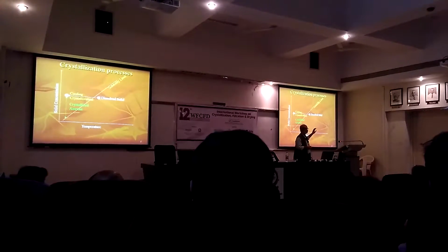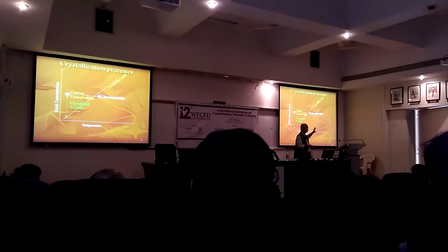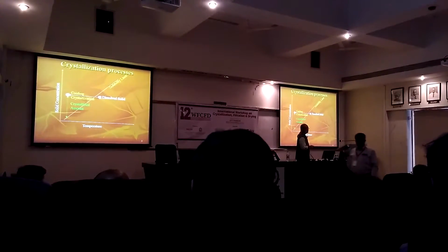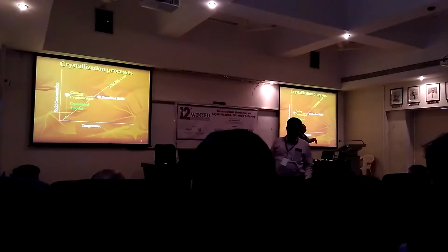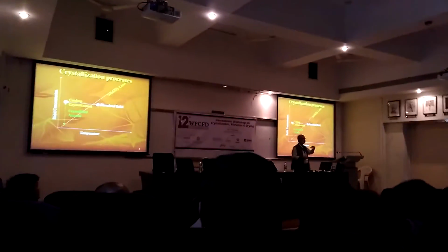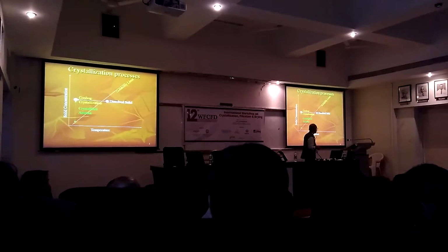I have not purposely marked the metastable region in here, which we will discuss in my second lecture, but here essentially cooling results in supersaturation. Now this supersaturation is supposed to precipitate out. How it precipitates out, in what form, whether it is in the form of powder or nuclei or crystal growth, is a different story. We will discuss it later.